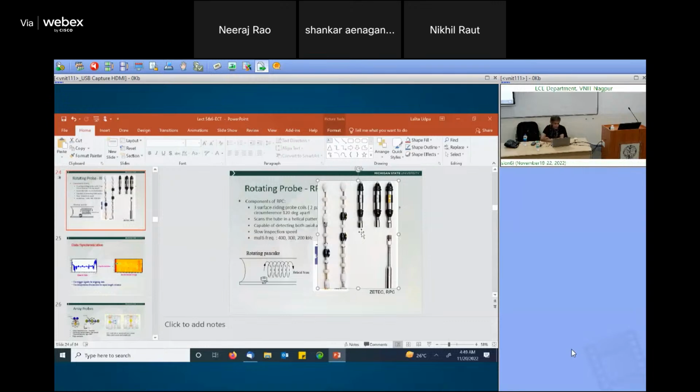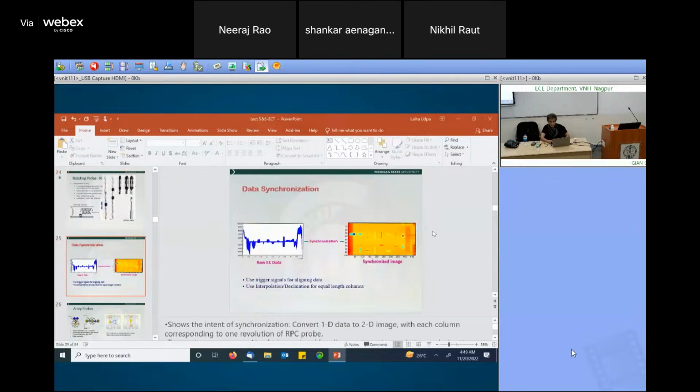So I thought you just wanted to see a picture of a differential coil probe. In the way back, they used to have a bridge configuration. So you have two coils in two arms of the bridge, and you look for the null signal. Now they have the differentially wound coils.